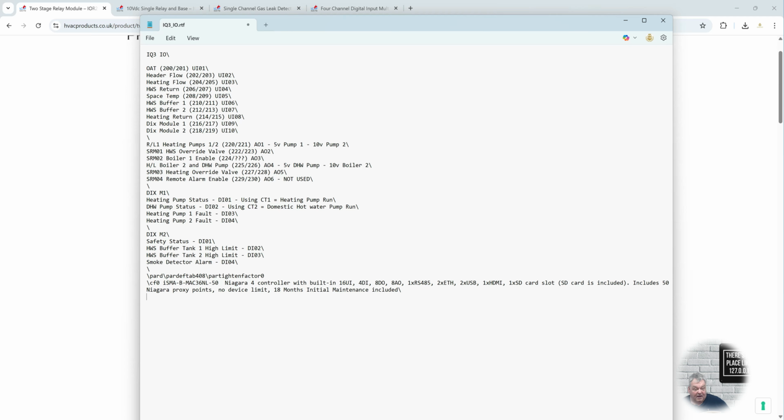So I think I will do it as per what we see, the DIX 2, but I may on site decide to wire, if it's not too far and I've got plenty of room on the cables. If not, I can put new cables in, but I'd probably prefer to wire these 4 items directly into digital input 1, 2, 3 and 4 off the MAC36.